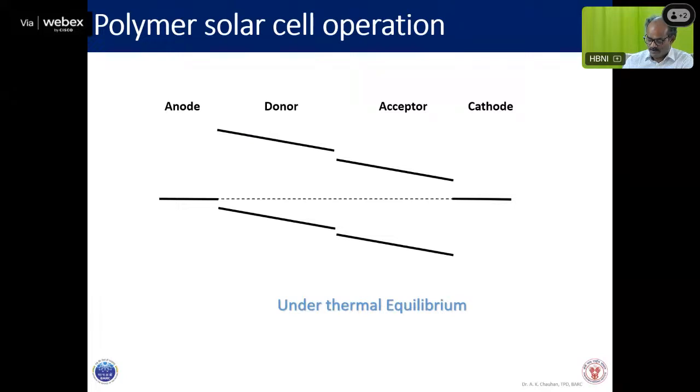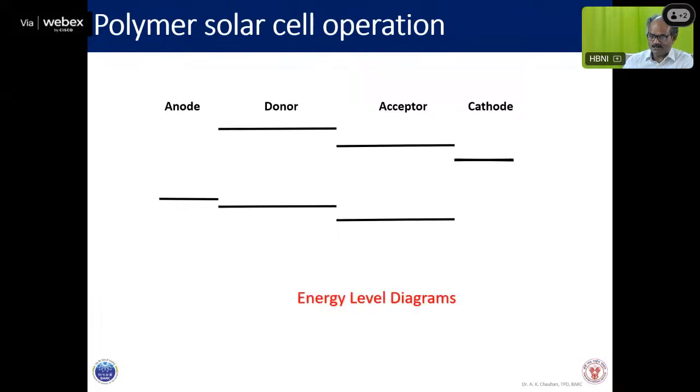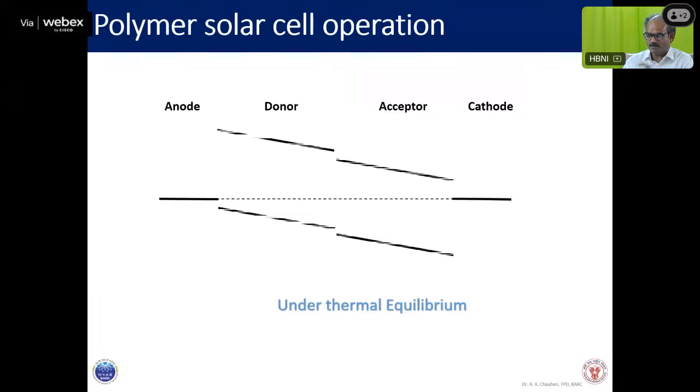So under thermal equilibrium, when we join them together, it was like this initially. When we join them, it becomes like this. This holds provided the distance is very small. If they are very long, then it will not apply because there will not be movement of the carriers throughout. Carriers should move from this point. So there should be a definite mobility when you want to draw such a Fermi level in thermal equilibrium to make it uniform.